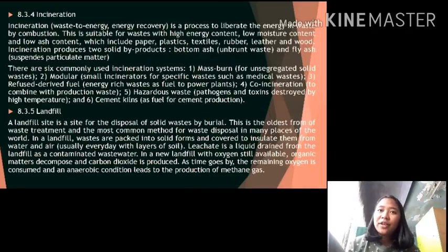8.3.4 Incineration. Incineration, waste to energy recovery, is a process to liberate the energy in waste by combustion. This is suitable for waste with high energy content, low moisture content, and low ash content, which include paper, plastics, textiles, rubber, leather, and wood. Incineration produces 2 solid byproducts, bottom ash, unburned waste, and fly ash, suspended particulate matter.